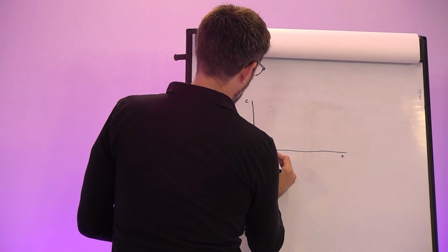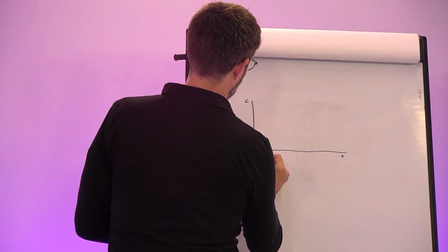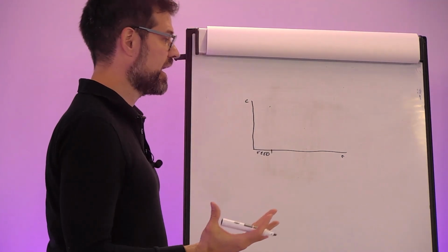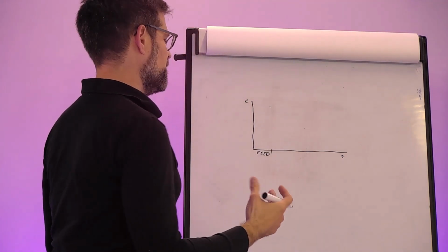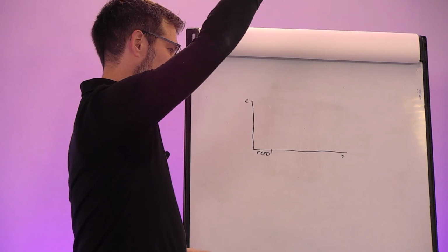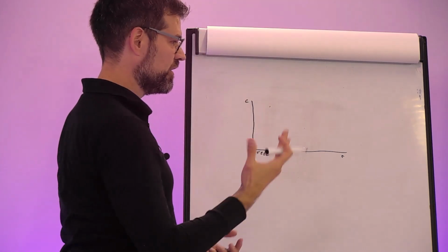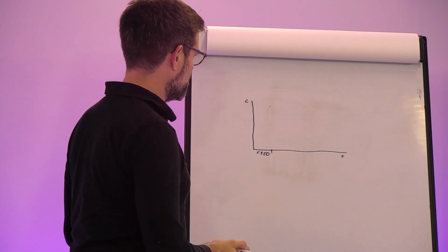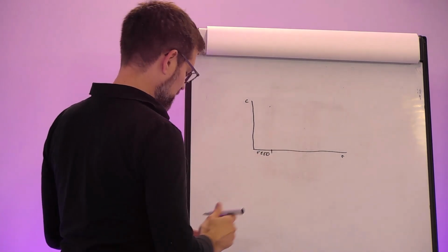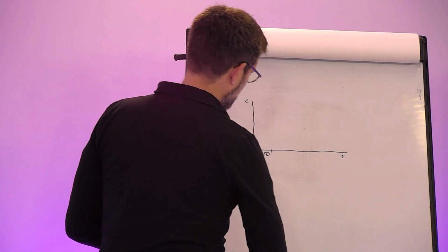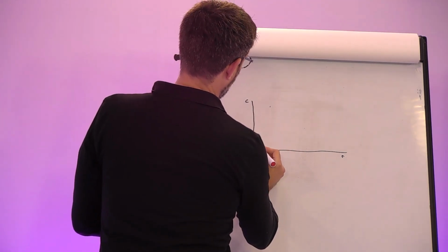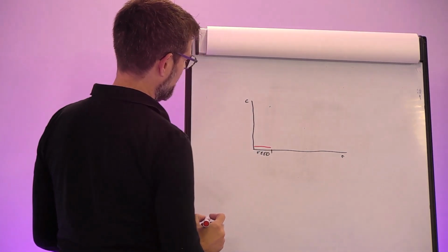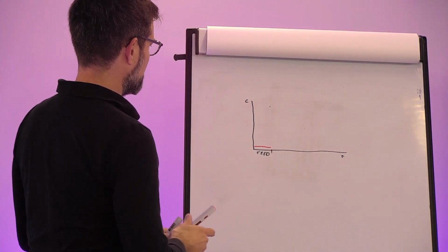We start the cycle with the feeding phase, so we feed influent to the reactor. Most of the time all the sensors are more at the top of the reactor, so when you are displacing from the bottom, you don't measure anything yet. For example, your ammonia concentration will be effluent quality during the feeding phase in the measurement. Then we start our aeration.